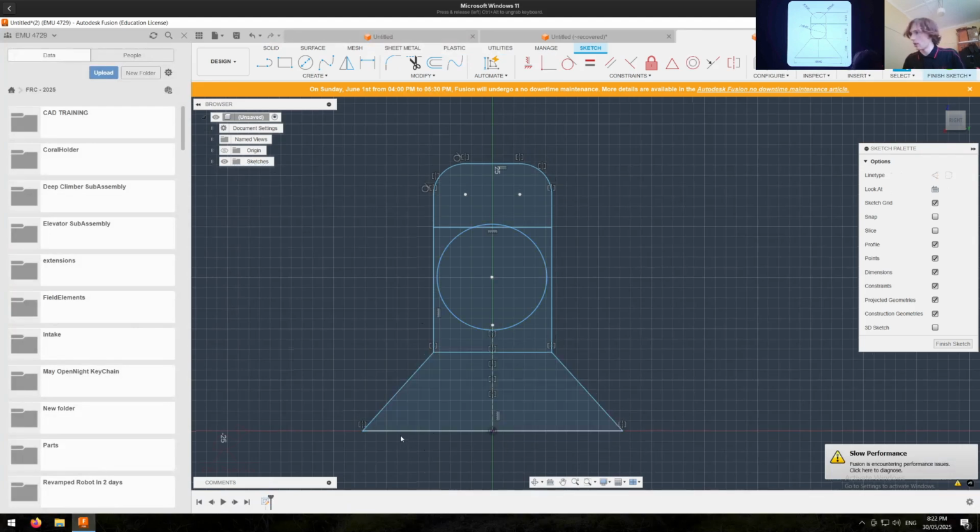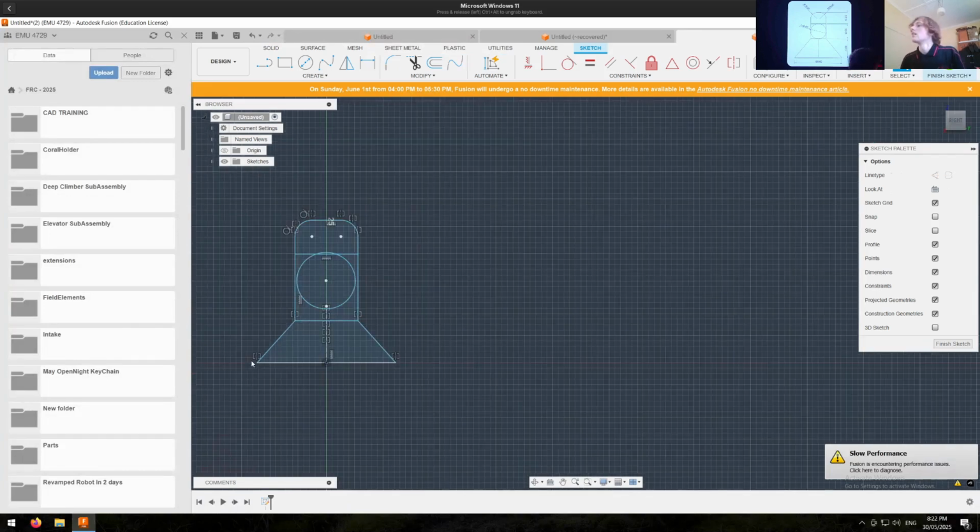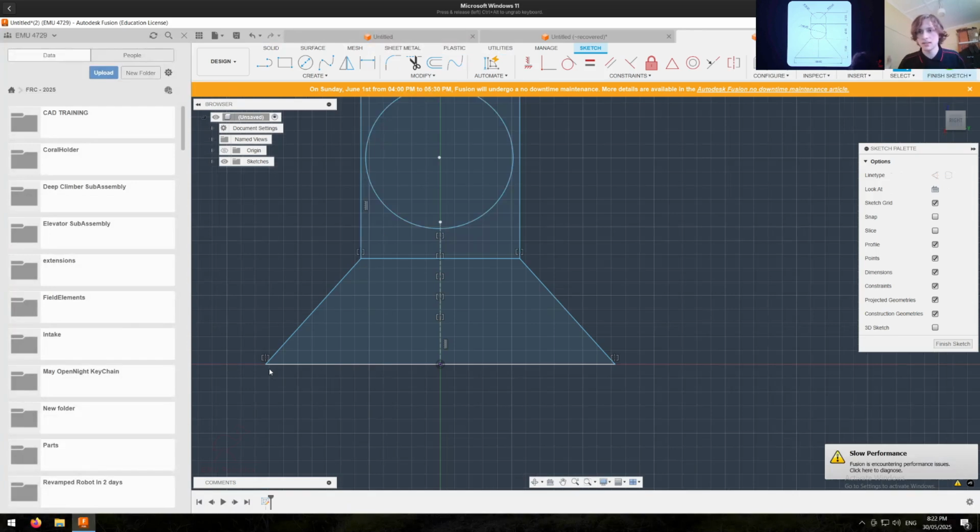And you see that? Oh, wow. That line has turned white. What does that mean? I have no idea. No, so white actually means that it is fixed. There's 3 different types of fixed. You have blue, which is completely unfixed. Then you have white, which means it's fixed in one direction because of constraints, but you can still extend it. Or you have fixed, I know, very technical, which is using the fix tool and then it turns green. And then it's not going to move no matter what you do. Like it'll still move like that, but I can select this and it's not going to move.